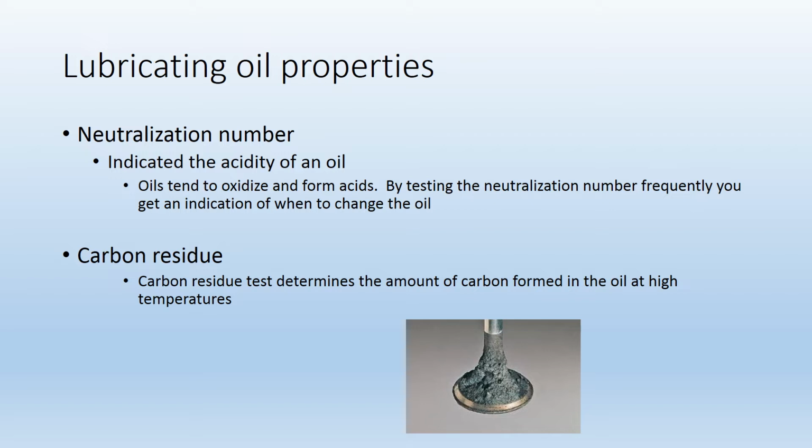Neutralization number indicates the acidity of oil. Over time, oil will become more acidic due to the oxidization of the oil. The ongoing neutralization number checks will form a basis for when to have an oil change.